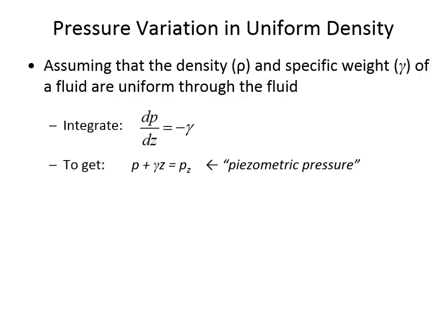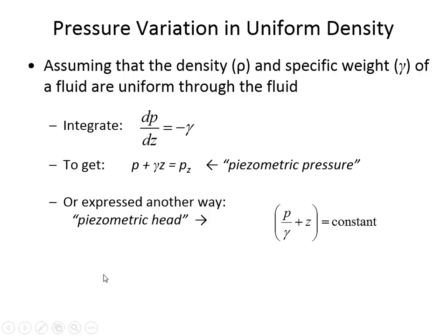We can integrate the hydrostatic equation to get something called piezometric pressure. And piezometric pressure is the sum of the pressure and some expression of the effective elevation above a datum. Z is the elevation above a datum. Or we can express it another way in terms of piezometric head. So let me just show you what I mean by piezometric pressure.